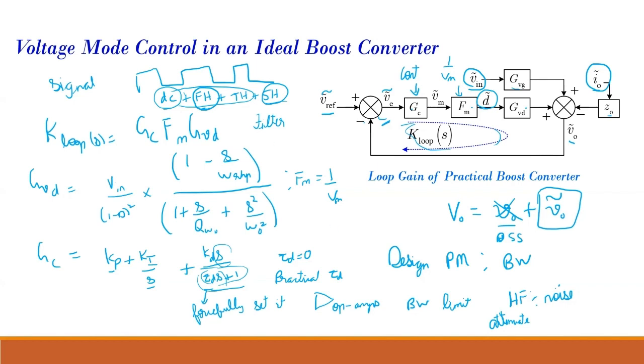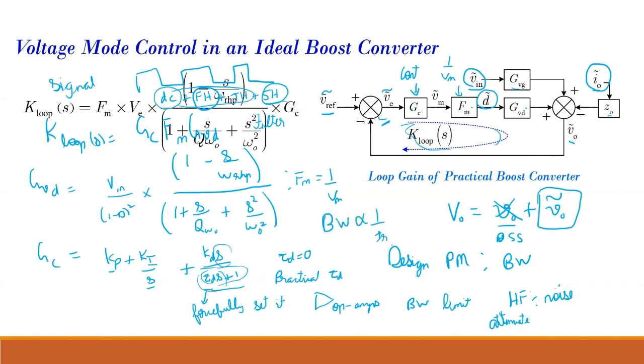So my bandwidth is inversely proportional to my rise time. If my bandwidth is very large, then my rise time has to reduce. As my bandwidth increases, my rise time will reduce. Okay. So that's the same kind of explanation we can have for tau d also. Yes, a similar explanation can be helpful for this.